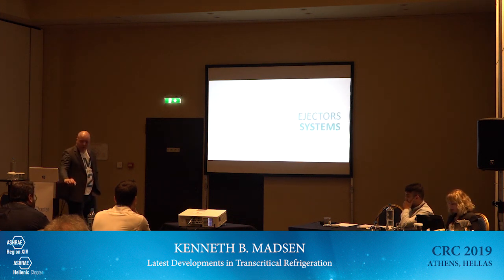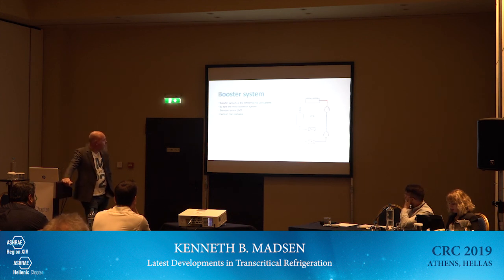So then a little bit about ejector systems. The basic cycle we are normally using is a simple booster system where we have LT and MT compressors, we have LT and MT evaporators, we have the gas cooler, and out of the gas cooler we do the first throttling in a high pressure valve.